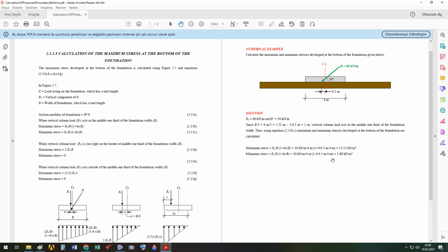And then what we do as a civil engineer, we will compare this stress value with the corresponding soil strength, soil bearing strength, which can be calculated using some parameters which are obtained from easy soil test, or which can directly be obtained from the SPT, standard penetration test.